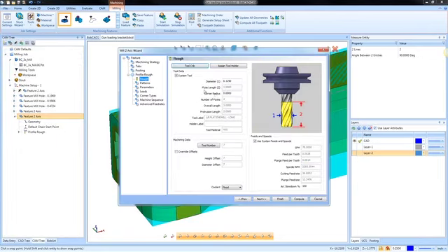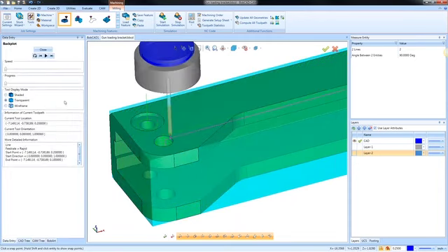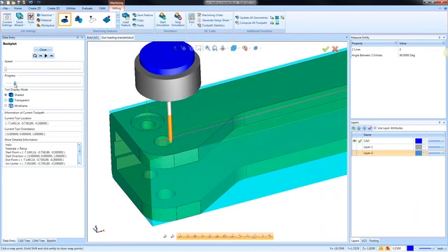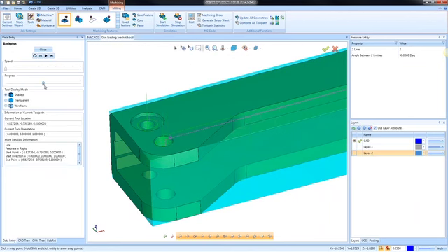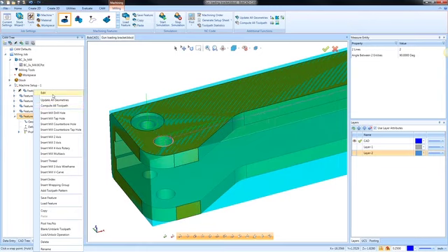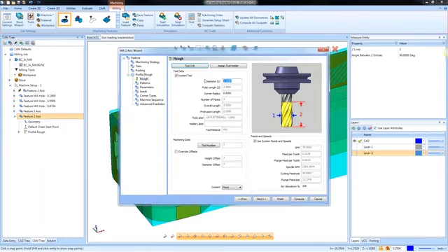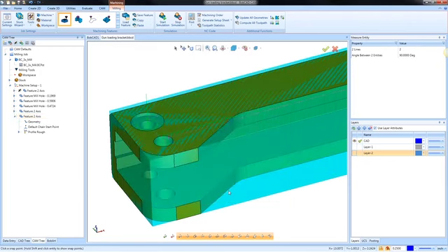Let me jump up my tool size. Okay, so I'm looking at this. I have an 1/8 inch tool to come in here and to helix these holes out, right? Which probably doesn't make sense. So I'm going to jump up in tool size. So I'm going to edit this. I'm just going to click on my tool, and then we'll make this a 1/4 inch, and then I'll recompute.